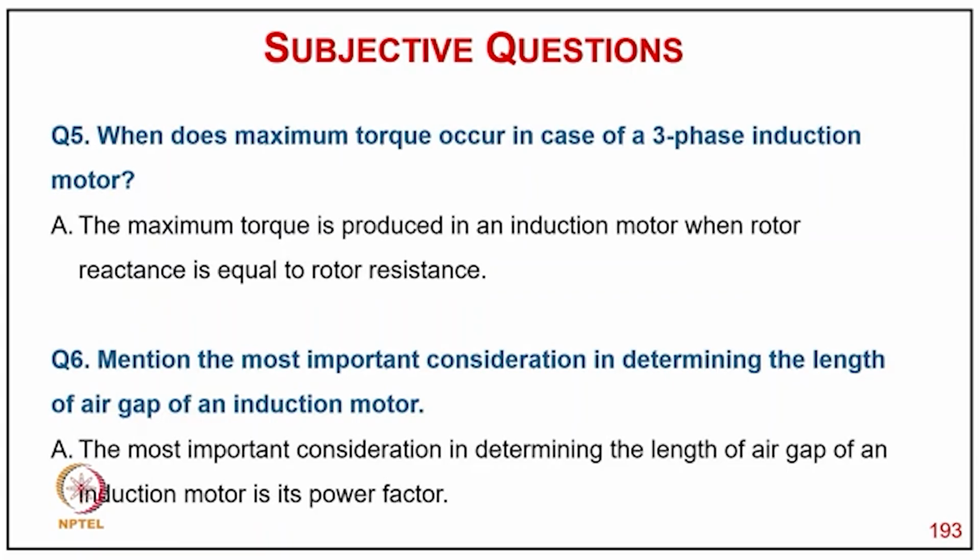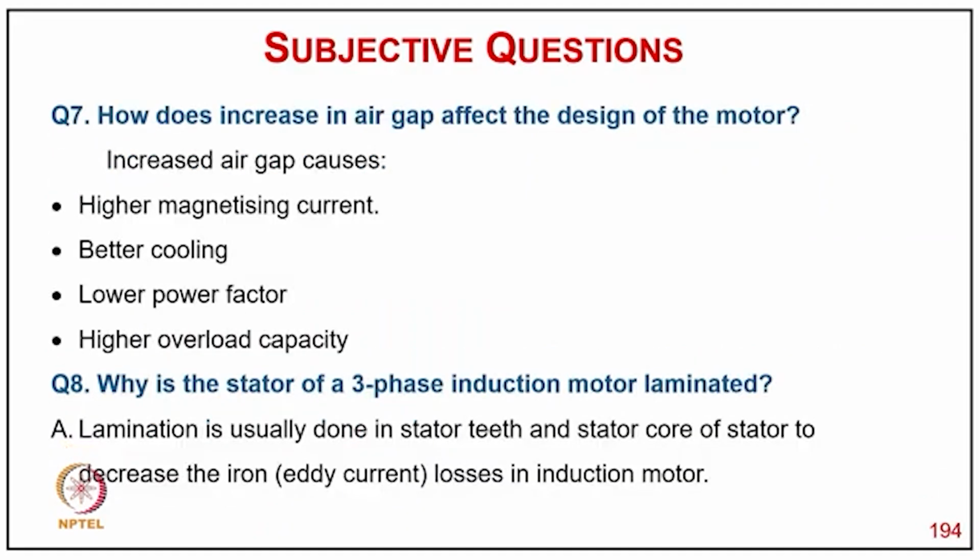The most important consideration is to determine the length of the air gap in the induction motor. How does an increase in air gap affect the motor? Increasing the air gap causes higher magnetizing current, a lower power factor, and higher overload capacity.